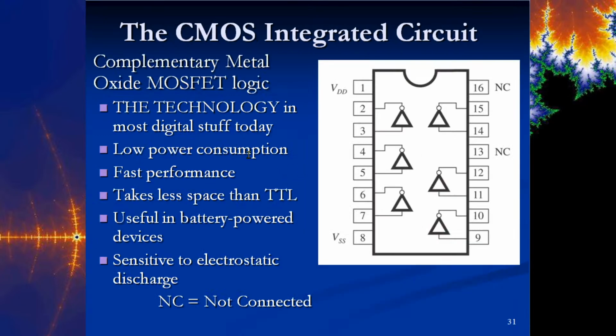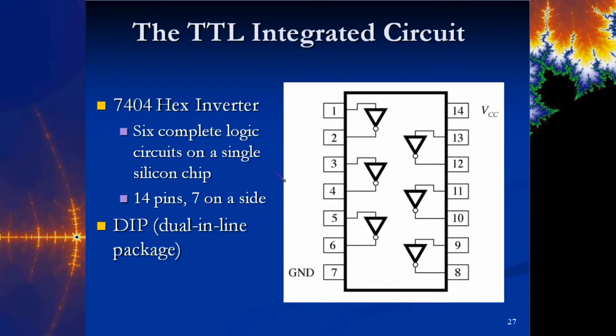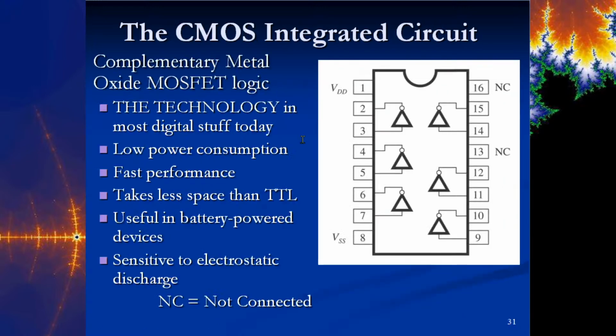All right. There also is what's called the CMOS IC chip. And so you see this one. The only difference between this one, well, there's a lot of differences, but if you just look at their pinout, this has 14 pins, and the CMOS has 16 pins. Okay, so it has a few that it doesn't use, like 16 and 13, and its power and ground are on different pins, and so you just have to get the pinout to figure out which one that is. Okay, now CMOS are sometimes a little bit more expensive, but that's because they're faster and they typically use lower power. They run off a smaller voltage.